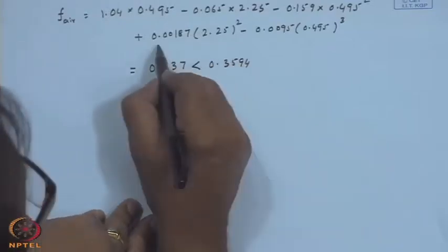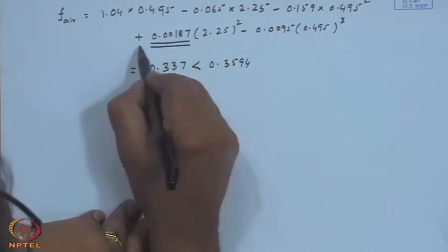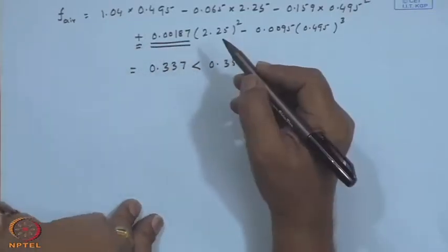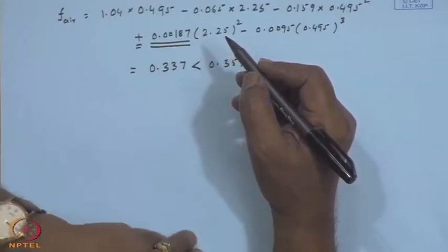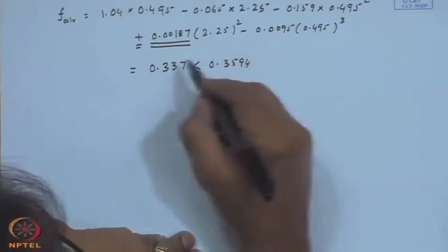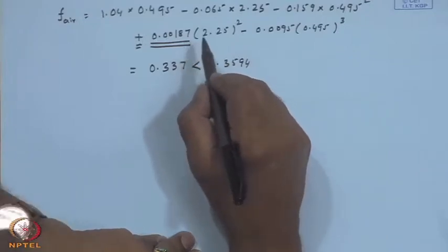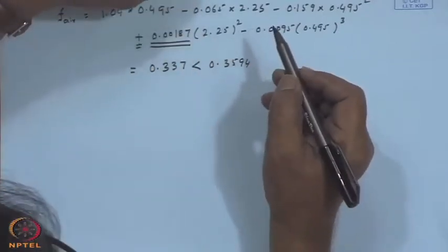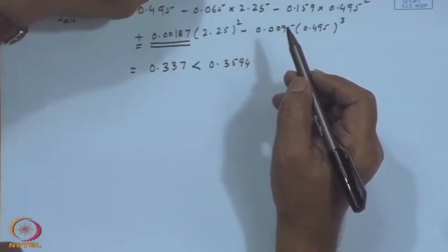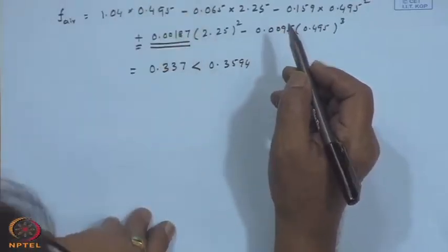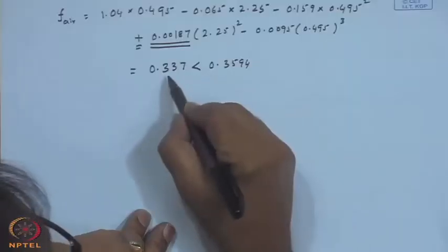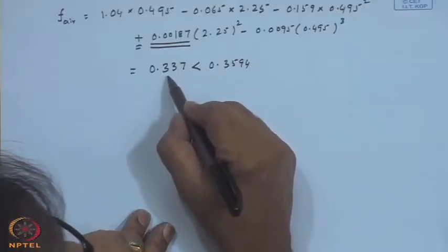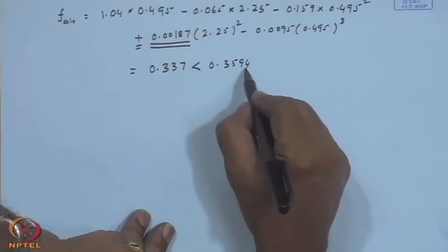So, this is actually attributed to this term with a plus sign, and x c has increased when the flow rate is doubled relative to the standard flow rate. One reason could be that people attribute that at a higher flow rate the storage is very much disturbed. So, stratification is not maintained, consequently the effective temperature goes down, making the effective solar load fraction lower than what it would be at the standard flow rate.